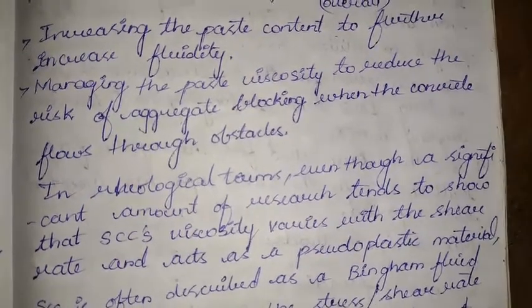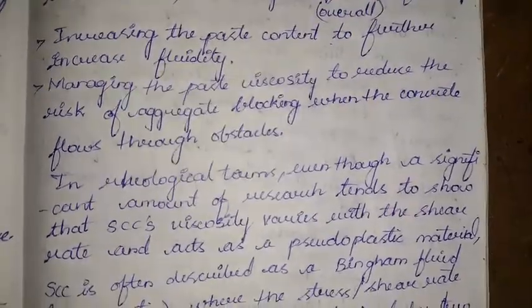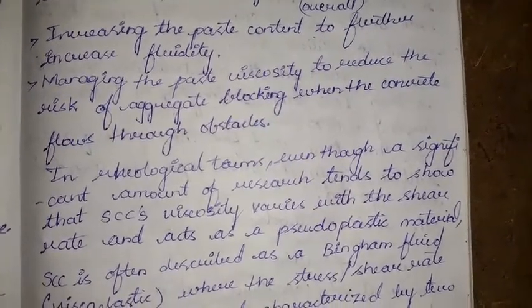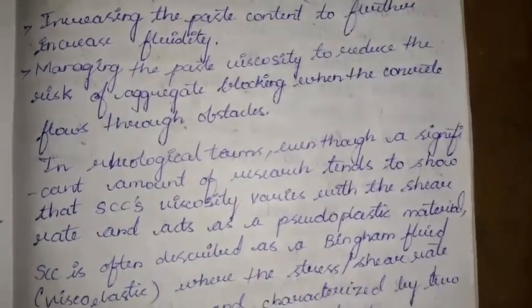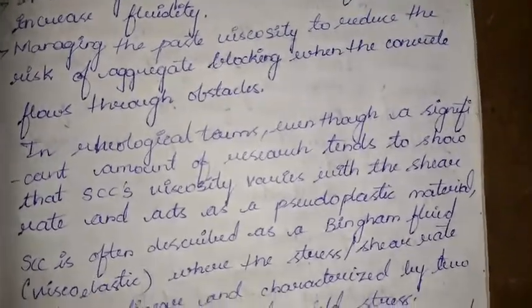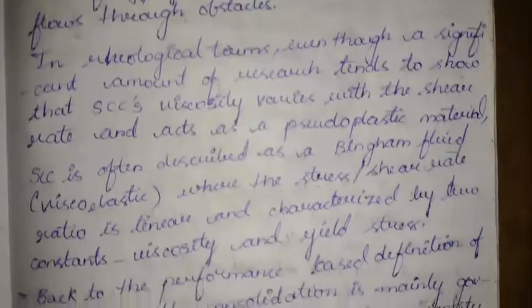Managing the paste viscosity reduces the risk of aggregate blocking when the concrete flows through obstacles. So we are adjusting the paste viscosity such that it is able to flow even in dense reinforcement with its own weight, that is self weight.